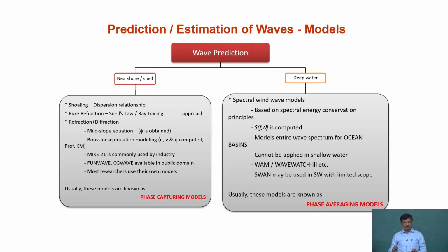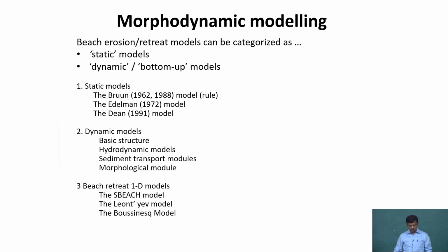Being at the near shore, both are very important for us. I will not say that the phase resolving model alone is enough for us, because many times the phase averaging model also will be a very handy tool for us to get the energy distribution across the entire domain. So, you should know both.